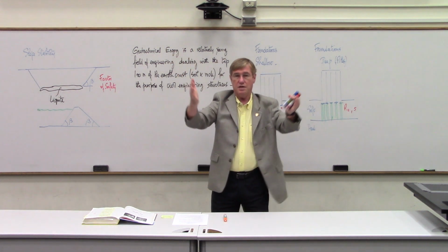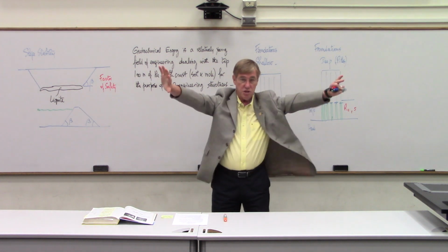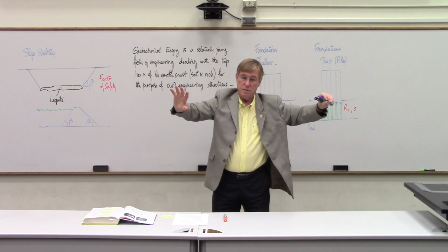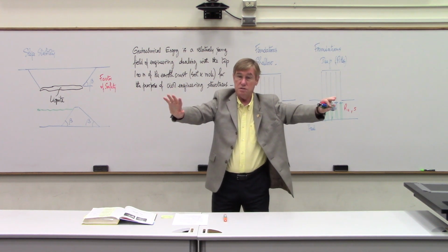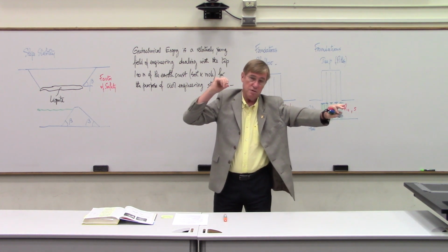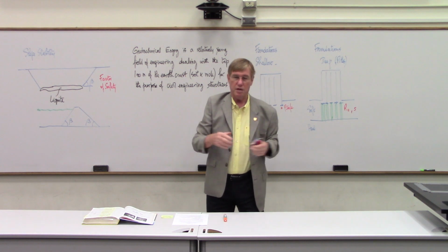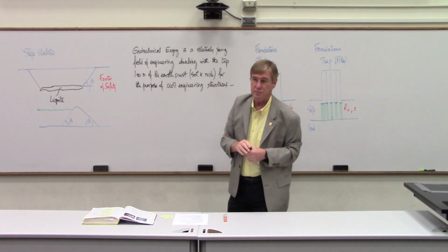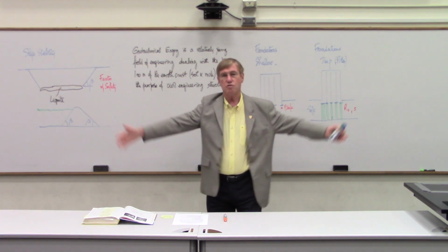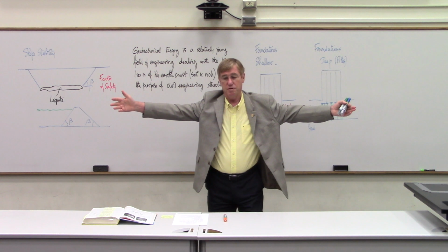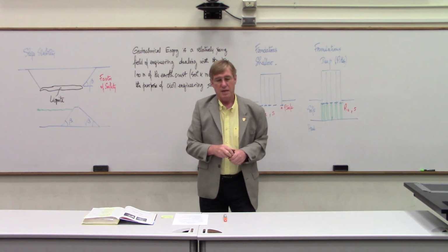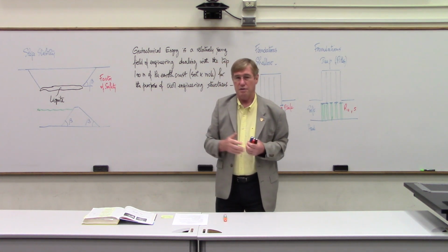If the valley is fairly narrow, then we build arch dams. They're concrete dams, they're arched, and they bear against the mountain sides or the canyon sides, and they retain the water through this arching, typically made of concrete. The example, the Hoover Dam. The other solution, if the valley is quite large for that river, then the arch dam is not feasible, too expensive. And then we use earth dams.